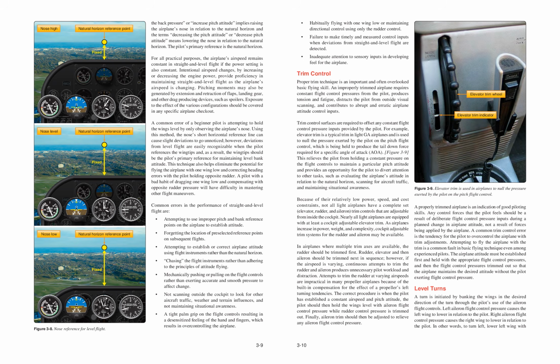Habitually flying with one wing low or maintaining directional control using only the rudder control. Failure to make timely and measured control inputs when deviations from straight and level flight are detected. Inadequate attention to sensory inputs in developing feel for the airplane.